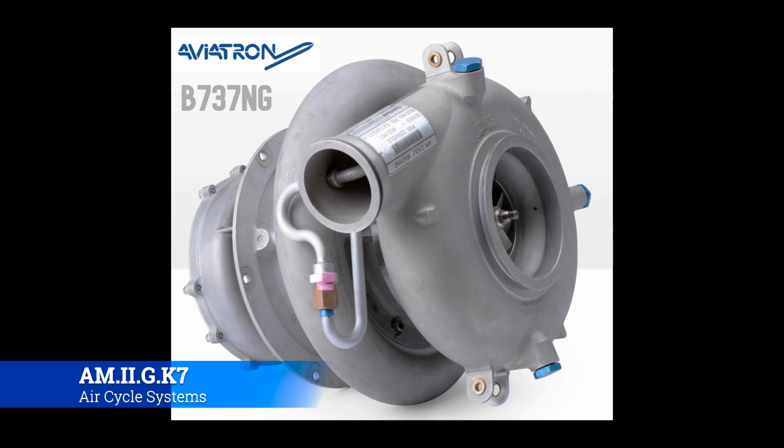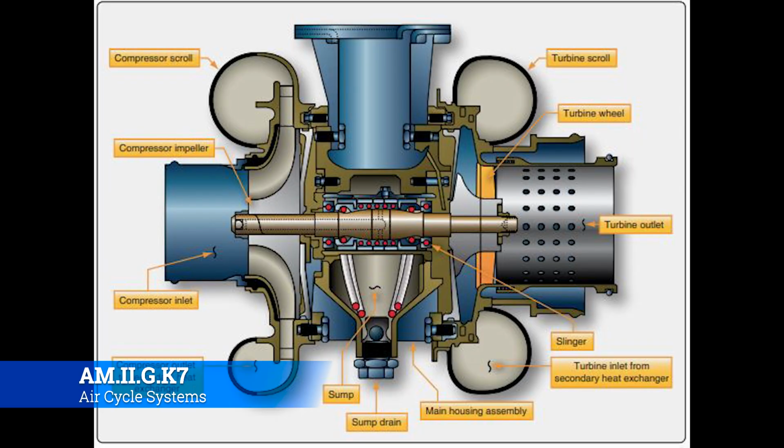All right, this is the heart of the air cycle air conditioning system. It's known as the refrigeration turbine unit. It's also known as the air cycle machine, or ACM. And this is one from a 737 NG, and that is an ACM. It's comprised of a compressor that's driven by a turbine on a common shaft.